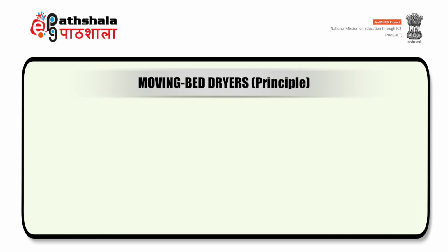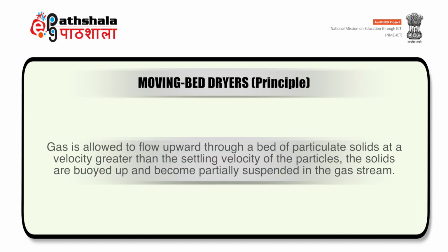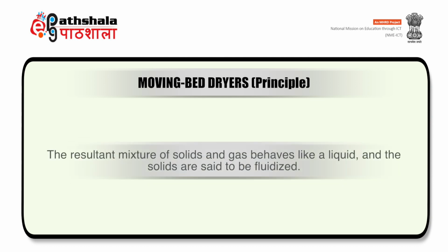Now talking about the principle. Here the gas is allowed to flow upward through a bed of particulate solid at a velocity greater than the settling velocity of the particles. The solids are buoyed up and become partially suspended in the gas stream. The resultant mixture of solid and gas behaves like a liquid and the solids are said to be fluidized.